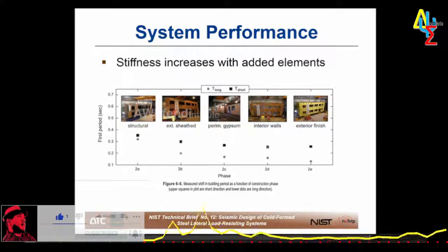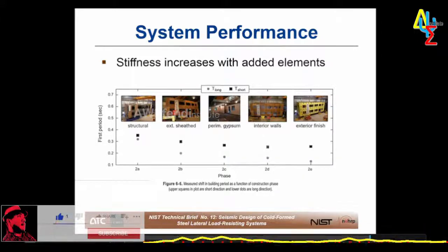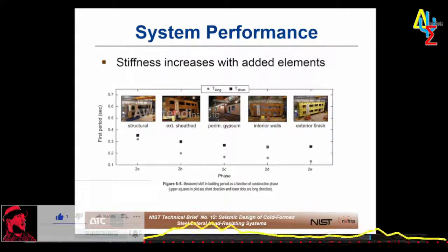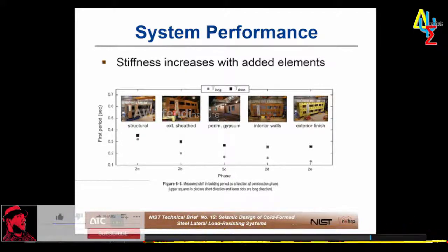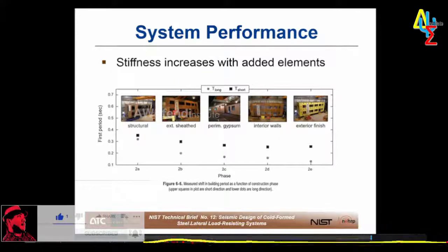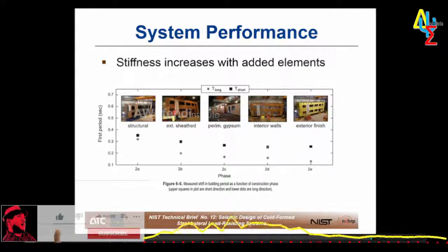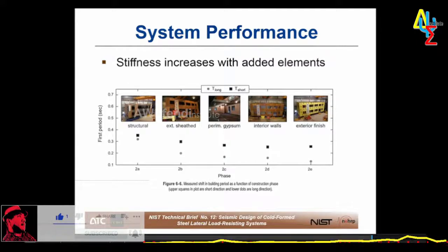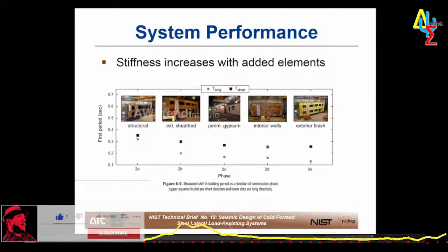So even the strongest shaking, which I believe came up to either 1.1 or 1.2 of the maximum shaking experienced in the spectra that we used from Northridge, only produced minor cosmetic damage in the sheathing around some of the openings. So we looked at that as good news and bad news. The good news is, behavior-wise, it really did well. I mean, it performed way better than I think any of the testers even expected. The bad news was that these methods that we use were not doing a good job of predicting actual behavior.